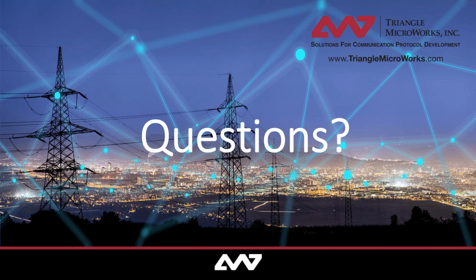And we also have a tool called Auto Data Changes, which is basically just dummy data. You go from analog values from 0 to 100. You can ramp, you can do sine waves. You can do different types of things like that. You can even do random values between a max and a min point, and you can periodically change it every second, minute, hour, however you want to configure that.